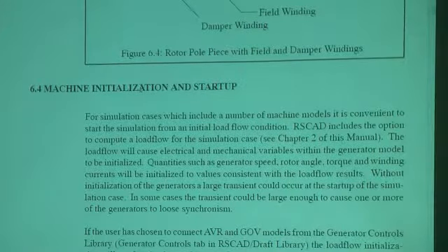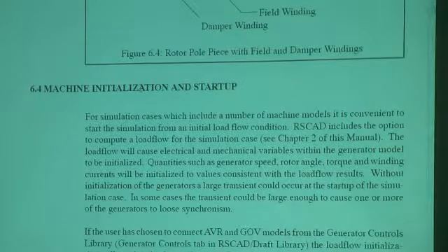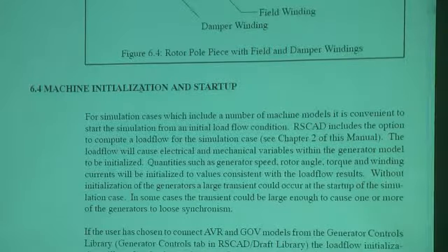If you have a large system with multiple generators and lots of controls, and you do not have a stable load flow calculation at the start, your system probably will not be stable, because you would have to start the system and have all of the generators set into a lock mode.